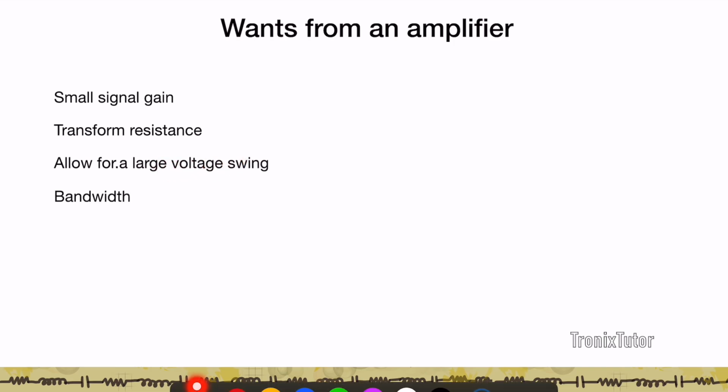Many a times you're dealing with signals over a certain bandwidth, as you want your amplifier to be relatively agnostic for signals within a given band. So we worry about the bandwidth of the amplifier. We talk about the stability. We don't want the amplifier to go out of whack for certain frequencies, for certain phases, for certain bias conditions. And we also want to think about the noise performance. That is, if there is a certain disturbance that the circuit encounters, the circuit should be able to recover from it.